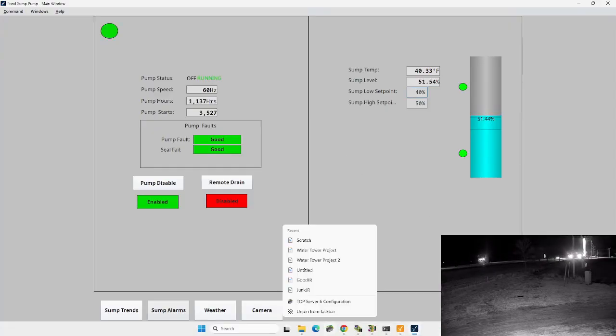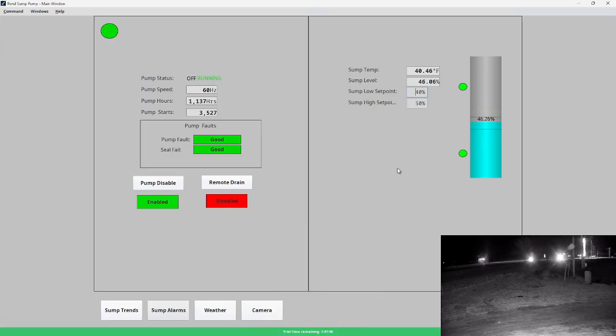We'll watch it spin down. Once it hits that 40% set point, it drains fairly fast. And it'll still pump out after it hits 40. 40 is just when the VFD starts to spin down. So now that the VFD has turned off,